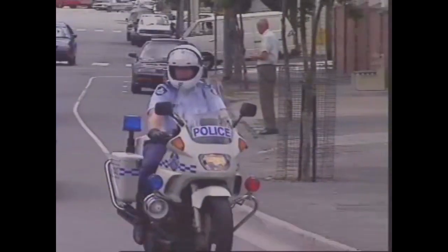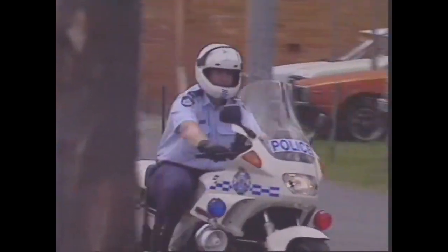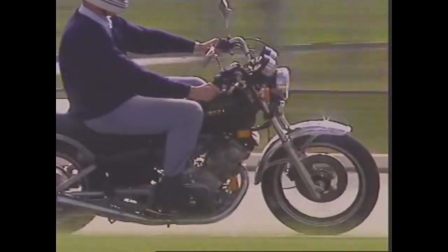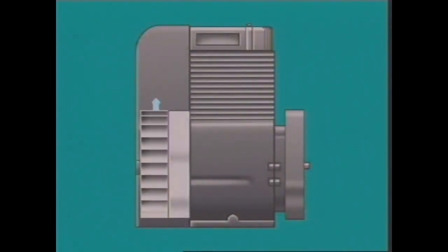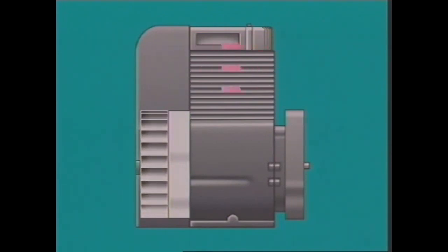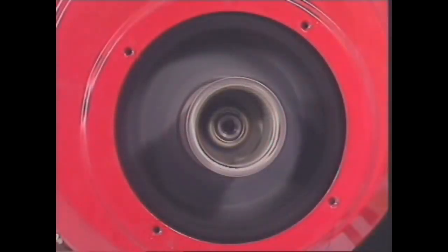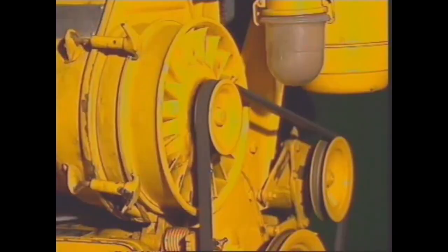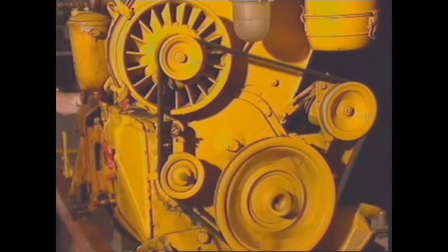At low speeds or during idling, heat builds up. Then the engine can use some help. Air should always be able to flow over the engine effectively. One way to remove heat is to use a fan with shrouds and ducts to direct air to the cylinders. There are many places to mount a fan and many ways to drive it. In this engine, it's on the flywheel. It's driven here by fan belts off the crankshaft.